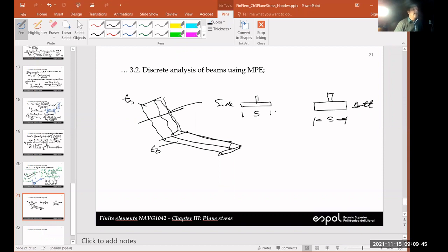So you need to calculate the sectional inertia of this and apply it in elements in this part, and another sectional inertia for the bottom. So yeah, you need to calculate different sectional inertia in general. It's possible that you have uniform properties. In that case, yes, it's going to be a single value. But in general, you need to calculate the properties of each section of the structure.